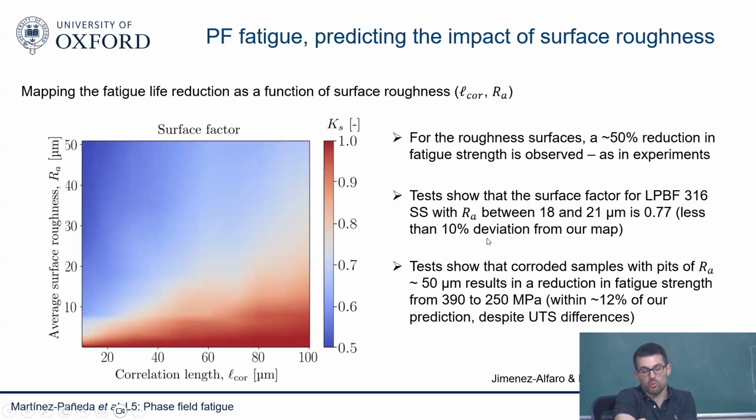So again, this is quite important because, as you can imagine, for example, in offshore wind turbines, in fact, the project that Sarah is funded for is based on offshore wind turbines, so they have a lot of pitting corrosion, and they want to figure out from that pitting corrosion what will be the impact on their fatigue lives. So you can run the simulations, and you can predict what will be the impact on the fatigue life. Okay, I think that's all for phase field fatigue.